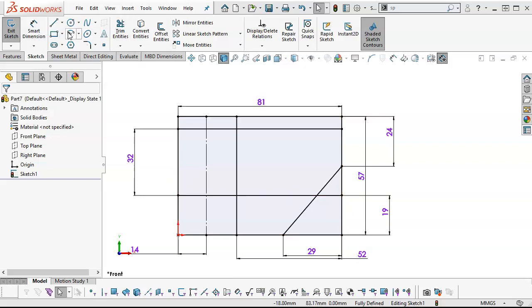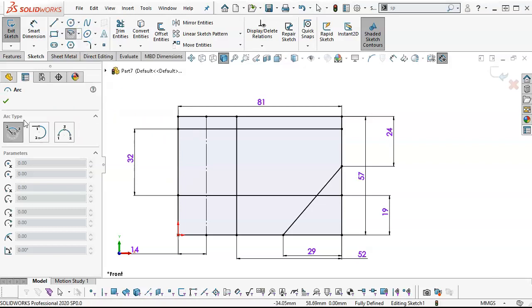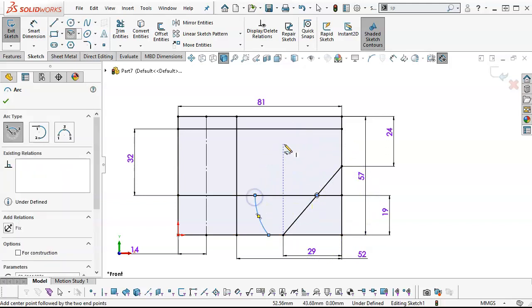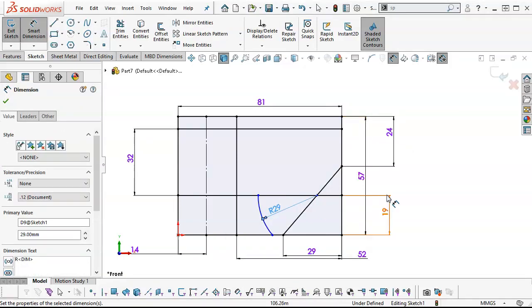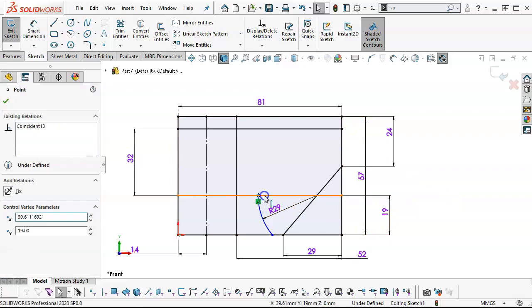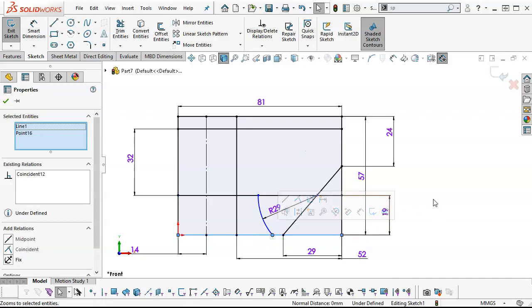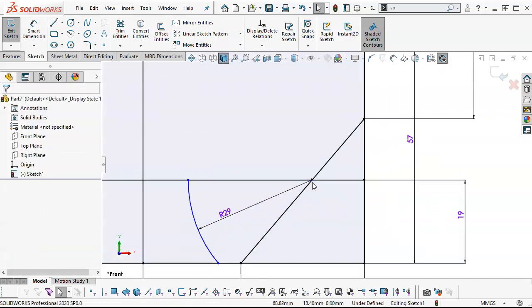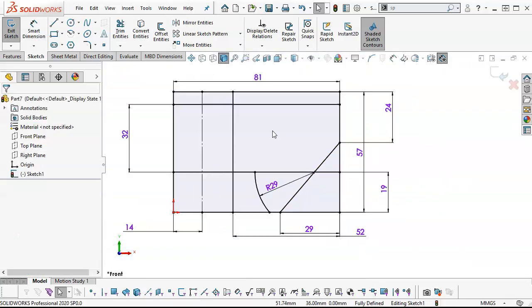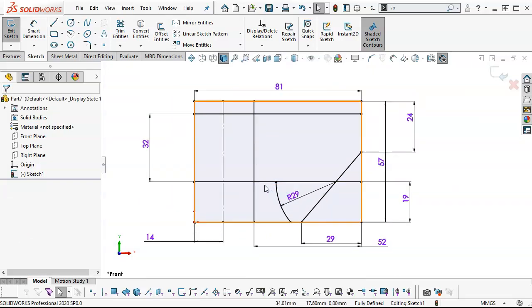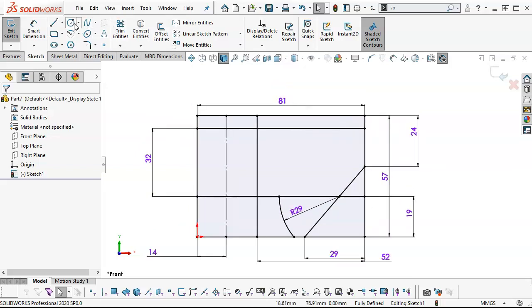Double check my number. And so if we were to go with the center point arc, should be able to drag out and up. Have it create the arc geometry. Place the 29. So that did not get coincident to the ends. So select, control, select, select, control, select, and don't need that one right now. We're going to just kind of drag back and forth until I find that coincident, and that'll give me that lower arc geometry back transitioning into the shelf. Alright, so we're ready for some arcs,